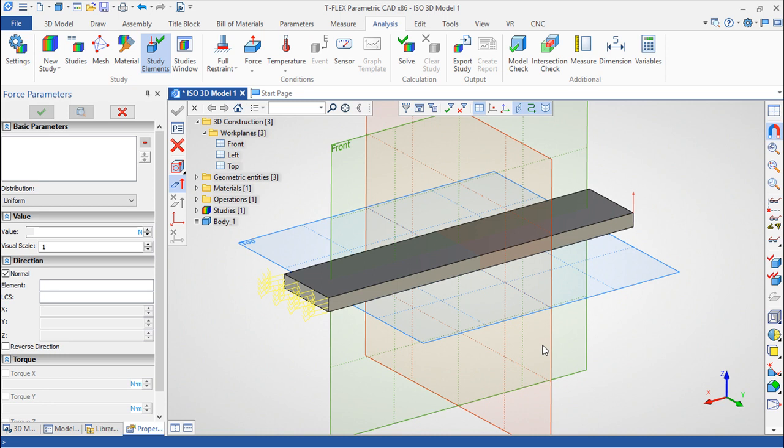It is very important, to obtain an accurate and trustworthy solution, for the user to have a very clear image of the phenomenon that is being analyzed. So it is of crucial importance to define properly the conditions that we have, being the restraints and the loads. It is extremely important, otherwise the results will not be what we are looking for.